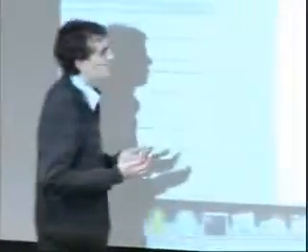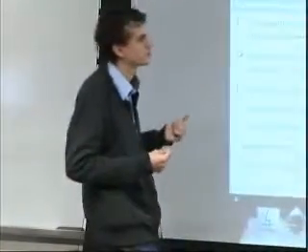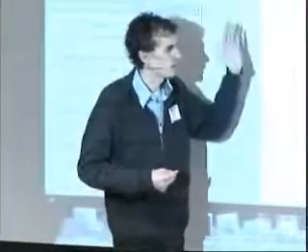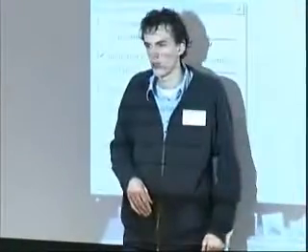You can do crossing detection for all these things while you're routing, but you take a penalty, like a speed hit, for it. So the way I've implemented it in here, and I'd probably advocate doing it, is to do all the initial routings and then look for problem cases. So do crossing detection there once for everything, and if there's particular things that you want to fix, you do it at that stage. Ideally in an interactive context like this, the user physically just selects something they don't like and says, hey, I want to reroute this connector and I don't want the crossings, and it fixes it.